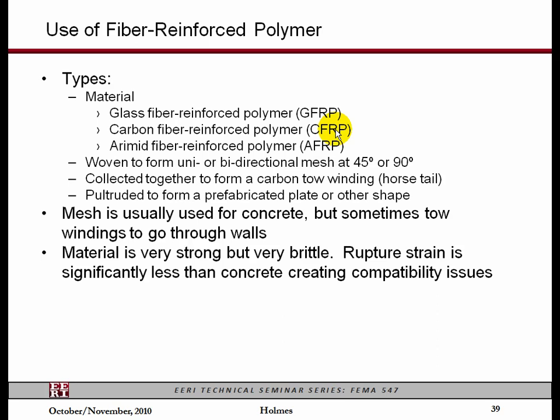Material is very strong but very brittle. The rupture strain is very much less than concrete, creating these compatibility issues that I mentioned. And under the theory that we don't really know how big the earthquake load is going to get, we strongly recommend in this document that you have a fuse somewhere that is going to yield in a predictable way before the FRP yields.